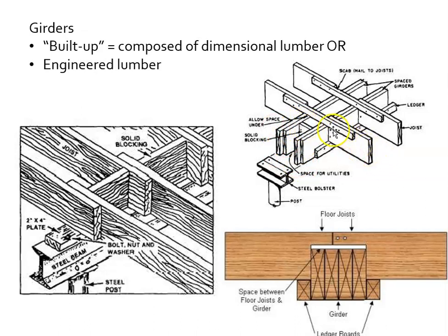Joists coming in that are ledged. That's common. I've seen that in older buildings. That's what we see here too. Here we see the girder, with ledges on the bottom side of each girder. Now we use metal joist hangers, but in vintage details and older houses, you'll see ledges down there. And then the joist will come and sit on the ledge.